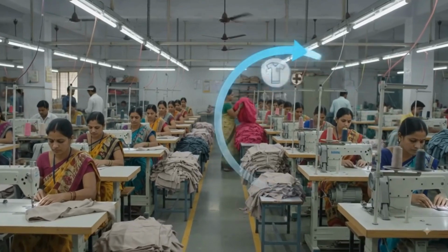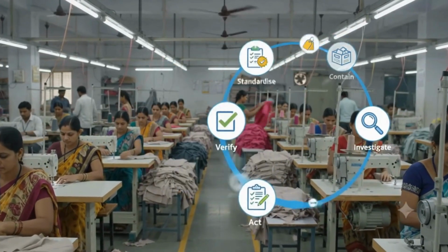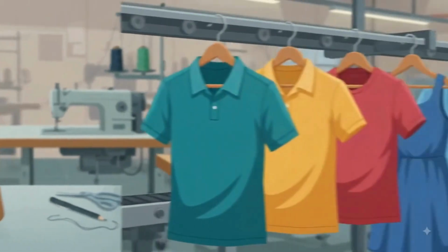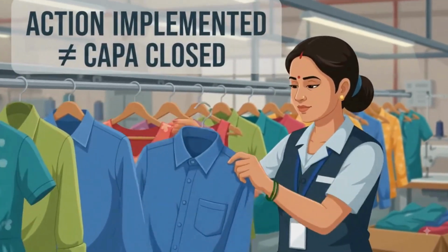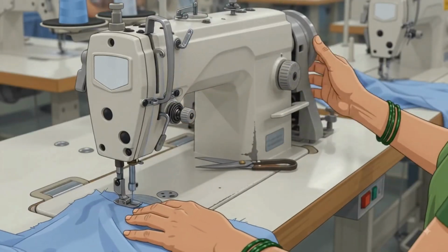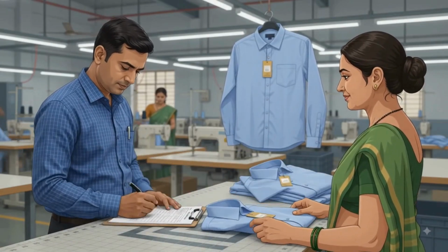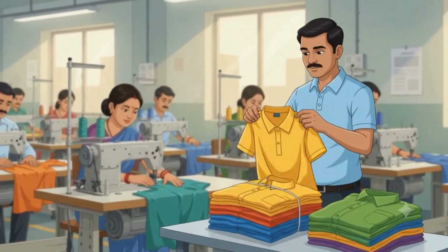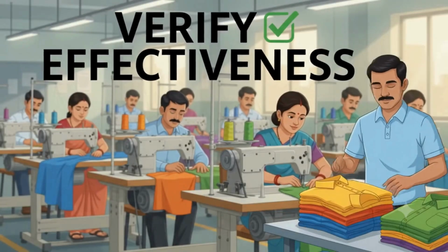CAPA is a closed loop: detect, contain, investigate, identify root cause, act, verify, and standardize. An action is not complete until evidence shows that it actually reduced or controlled recurrence. Production restarts only after a trial seam and first garment are checked against the approved sample. Subsequent garments are inspected at intervals to confirm that seam puckering has not returned.